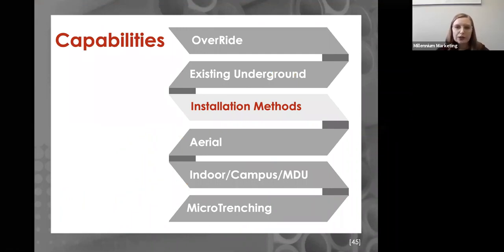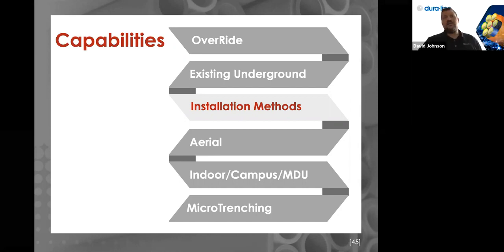David, real quick, we have a couple of questions. If you're installing multiple single microduct into existing duct that has the fiber in it, how do you keep it from getting tangled, as fiber doesn't always lay flat? Yeah, great question. So, over time, that fiber can relax as it's been in the network and so forth. There isn't any way to prevent it. It is more preventable by the solution that we do with pushing air through there.